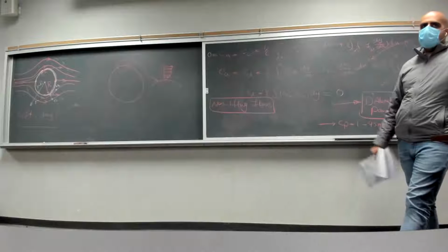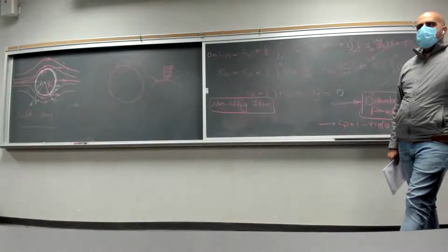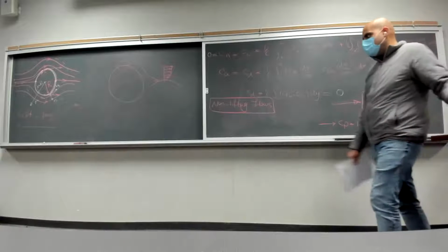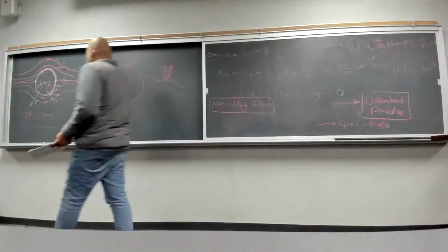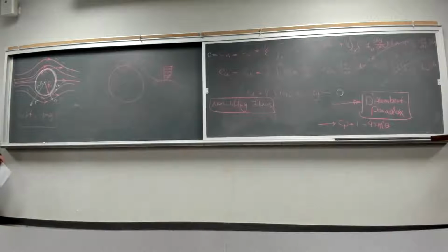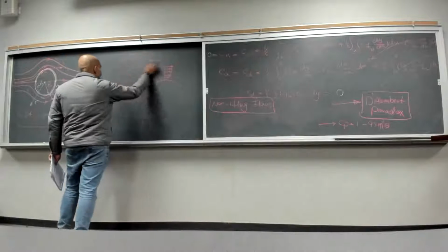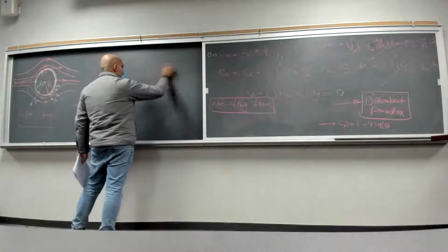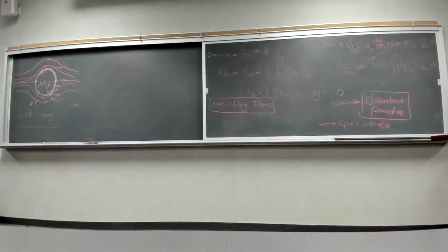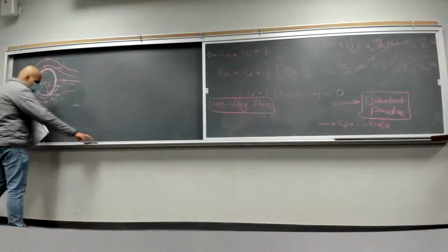This is one of the few cases in which the inviscid assumption is going to give you such an inaccurate result. In other cases, we won't really see this inaccuracy. We can get a good estimation of drag force in some other cases. We're going to come back to boundary layer analysis and their effects on friction drag, pressure drag, all of those things, later at the end of this chapter, where we will have a detailed analysis. But let's move on.